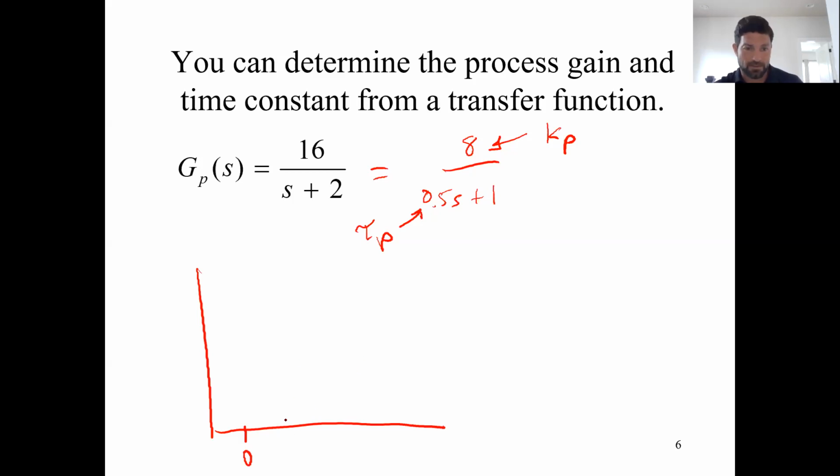I'm just going to put this on start, t equals 0 right there, and give a few increments in terms of tau p, 1, just for these. This is in terms of time, maybe minutes. So we have 1, 2, and we'll call this time in minutes. Again, the transfer function would have to have units associated with it. This is typically going to be something like how much change over something, and the units on the s will be in terms of time. So it could be minutes or seconds or hours, depending on the process.